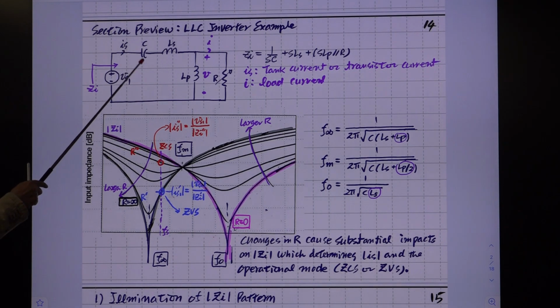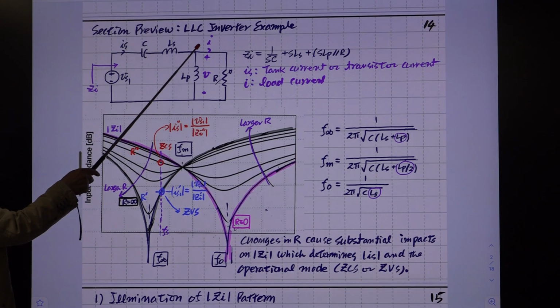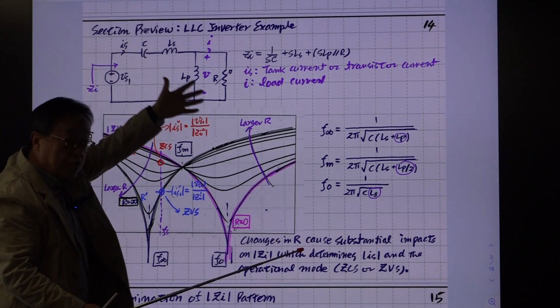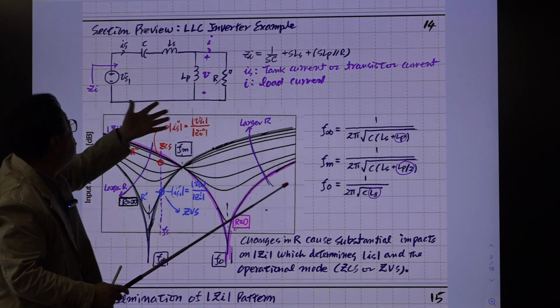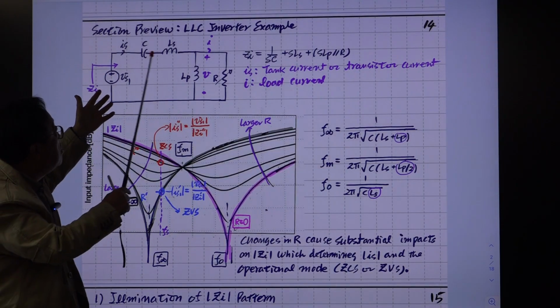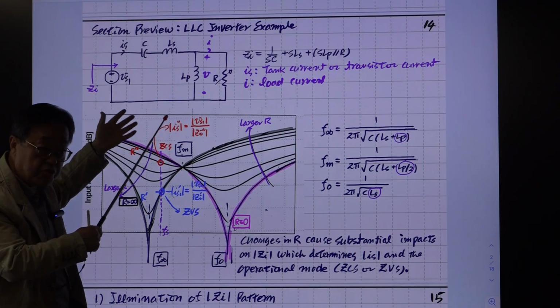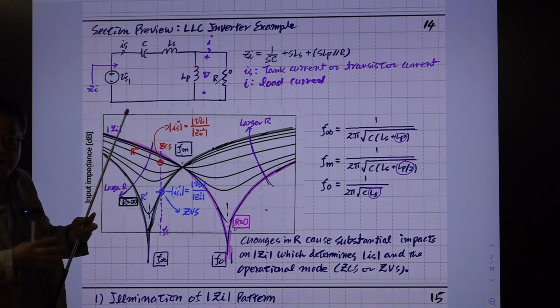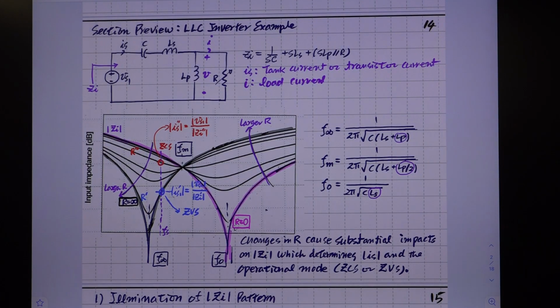Okay. Not all of the tank current goes to this path. Just part of the tank current becomes the load current. Most of the tank current is just circulating through this channel, idling through this channel, but that current is required. With that, we have the resonance characteristics of this resonant tank. That provides the frequency selective bandpass characteristic of this tank circuit. All right, that provides ZVS switching.